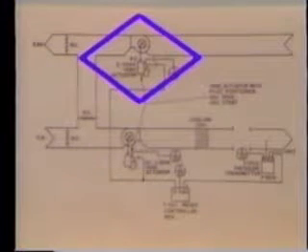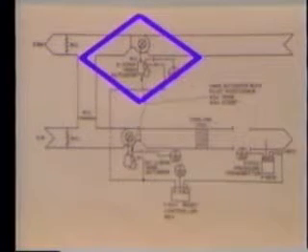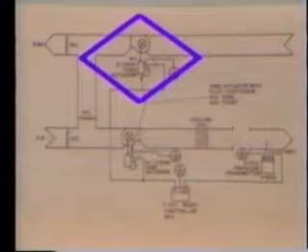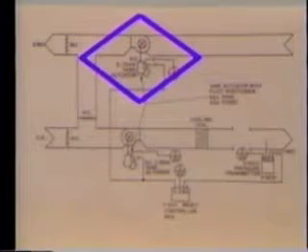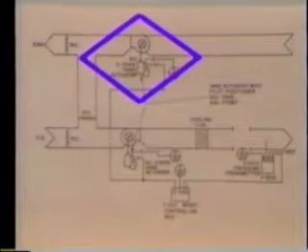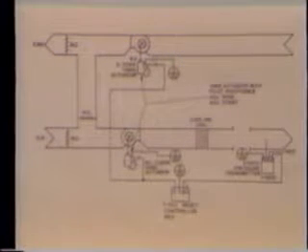A pilot positioner with adjustable span and starting point permits adjustment of the return fan capacity for perfect match at these two system capacities if fan and capacity modulating devices have similar characteristics. Volume differences can be maintained within close tolerance. On these simple systems, this control arrangement has been very successful.